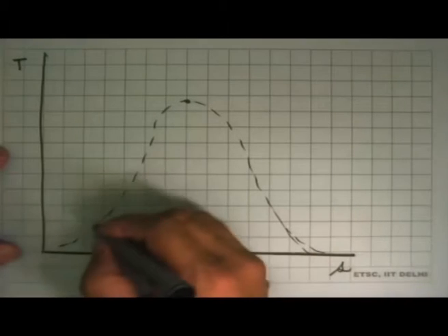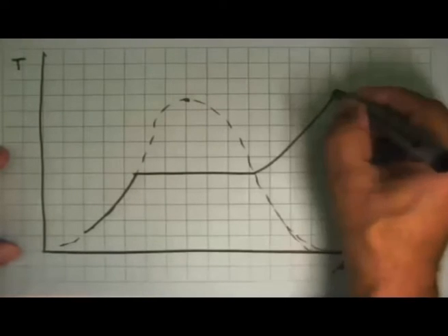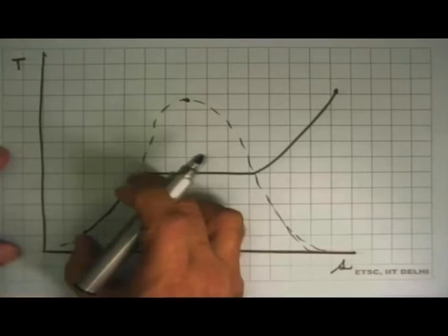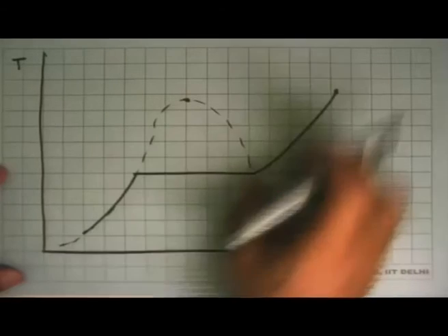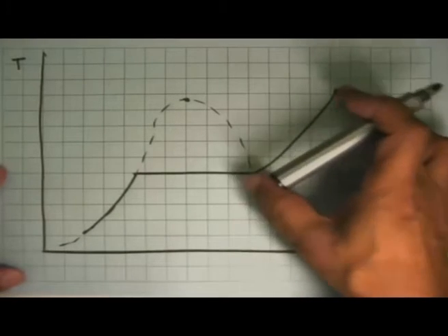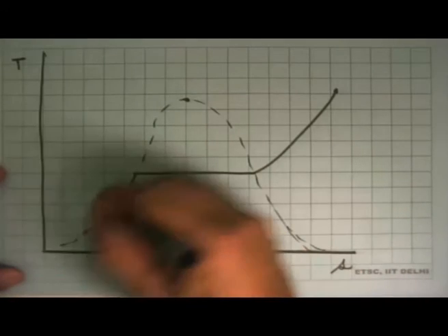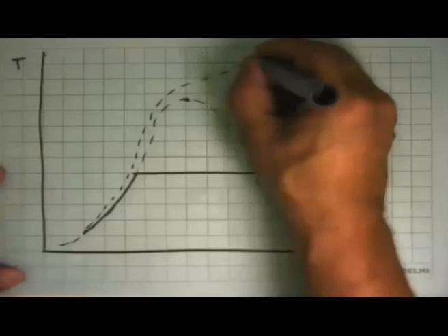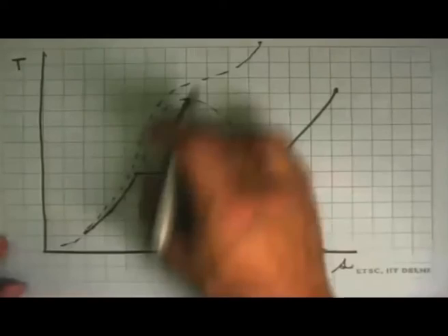If we design something to generate superheated steam, we have to design something that will heat the liquid part. Then we design something that will do the evaporation, where there is a big phase change taking place. Phase change means a big volume change. And then the superheating part. So the design of the boiler becomes a three-part design. But if you have a supercritical boiler, this will go off like that. Which means I don't need to design three different things, only one thing.